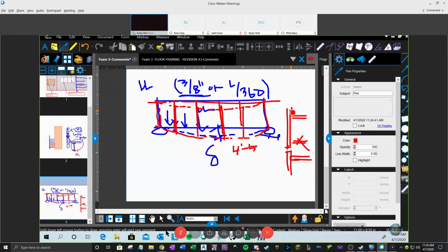Maybe I have to bring up more detail, but they are laterally supported at one point and gravity supported at another point. So the glazing curtain wall system is usually hung at the top and laterally restrained at the bottom.